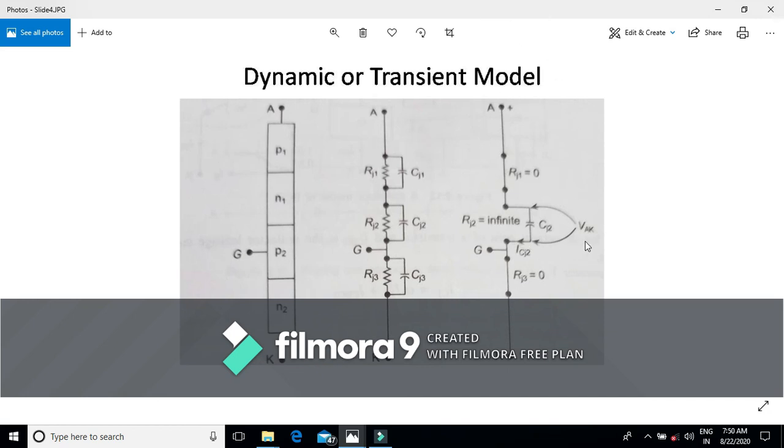That means if the rate of rise of anode to cathode voltage is very high, this may result in an increase in the junction capacitance current. This capacitance current behaves like the gate current, and it may result in an increase of the anode current. And once this anode current reaches the latching level, the SCR will remain in the on state even if no gate current is applied.